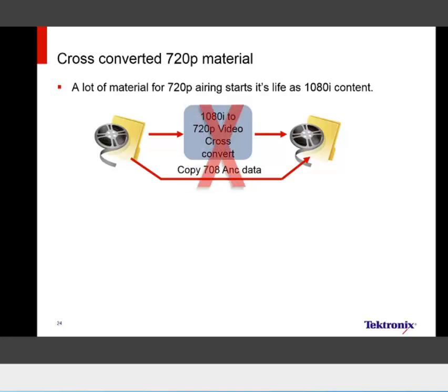The problem with that is that you will have 1080i captions sitting in your 720 material, and instead of sending out 9600 bits per second, you're going to be sending out 1400 bits per second in the caption channel, and you're going to OD most caption receive buffers.